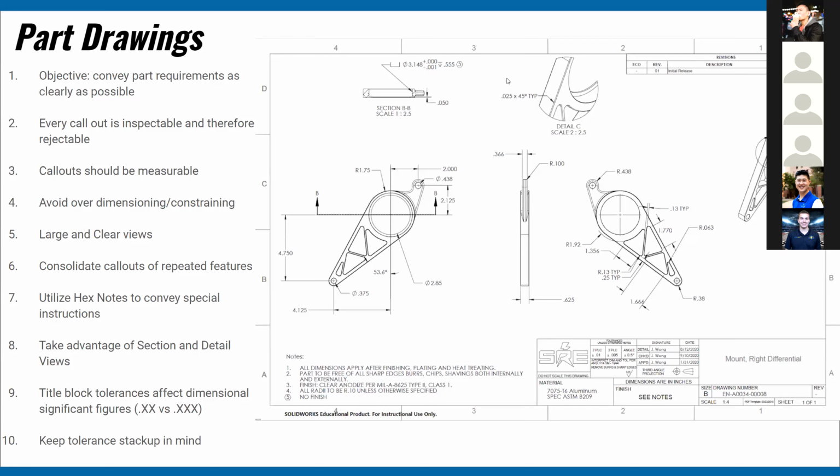Yeah, so in this case, for chassis or frame, body, and suspension stuff, I think it's important that whoever's making the drawing does at least understand what the function of that part is, so you can understand what kind of tolerances you need to put on that. Even if you aren't a designer, you should understand what it needs to do. It's fit, form, and function. And if you don't understand it, talk to a lead. Maybe they can clear some stuff up with you. But to be actually accurate with your drawing, it's necessary.